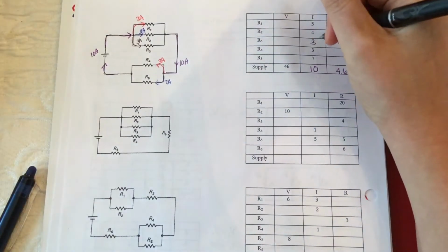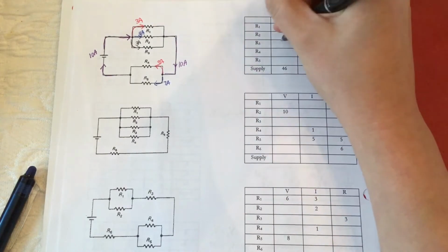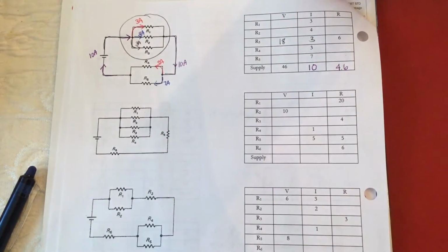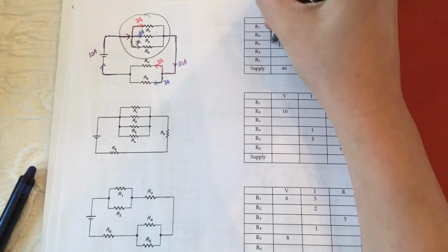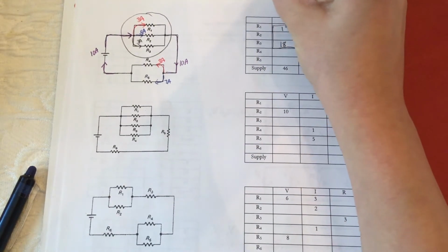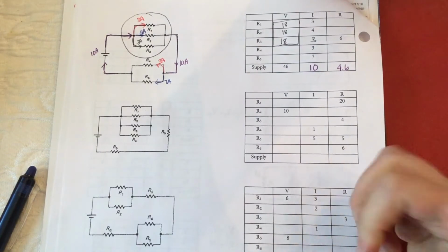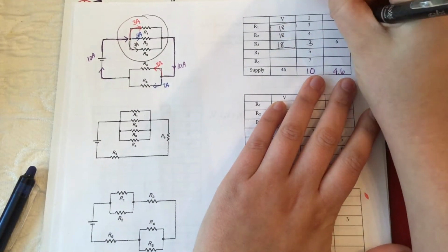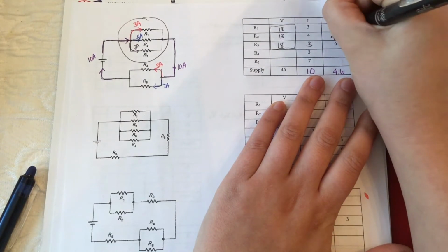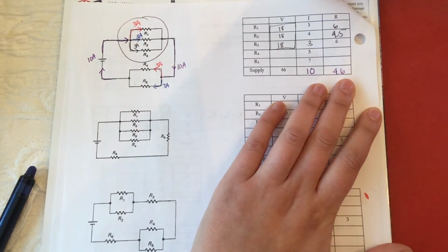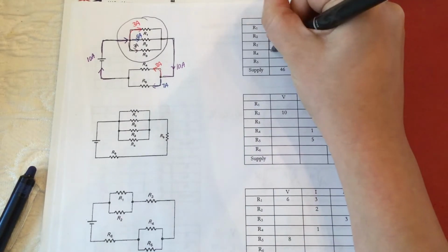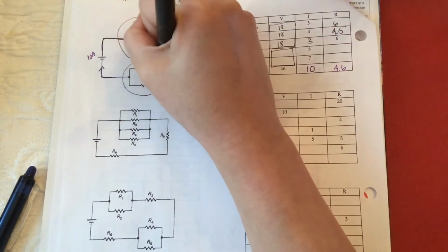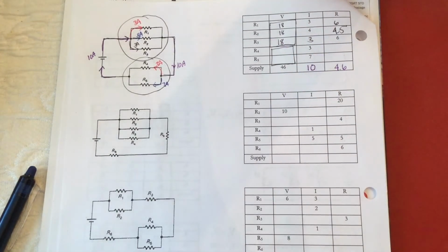Multiplying across this row using Ohm's law gives a voltage drop of 18 over all 3 resistors that are in parallel here. These 3 resistors have a voltage drop of 18 each, which allows us to find the resistance using Ohm's law dividing across rows, 6 and 4.5. Finally, we can get the voltage from R4 and R5. These two should be equal to each other because they're in a parallel circuit.